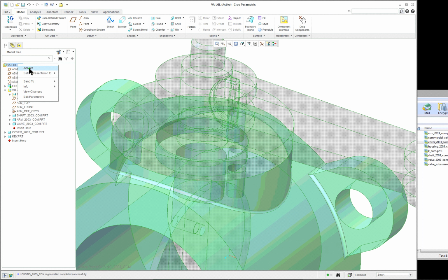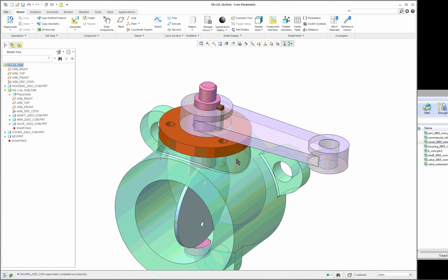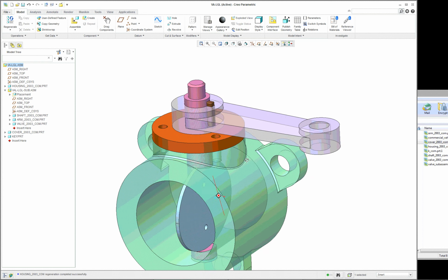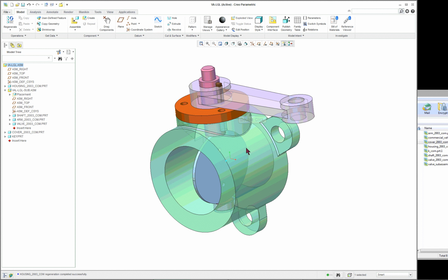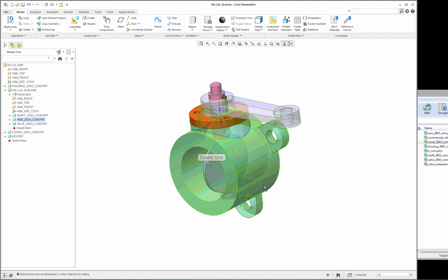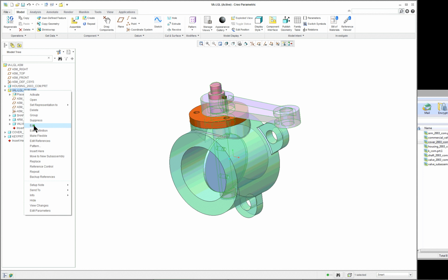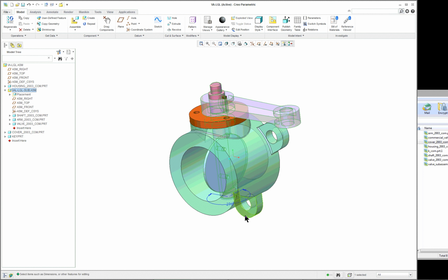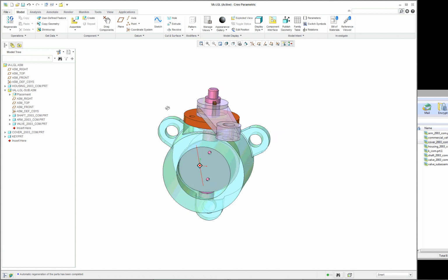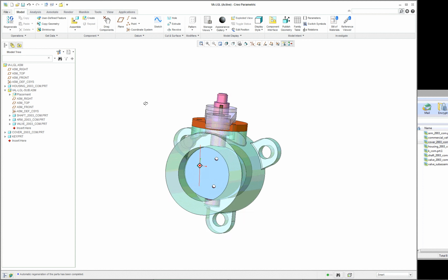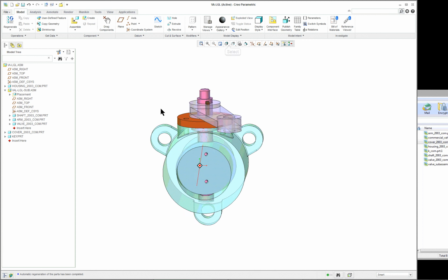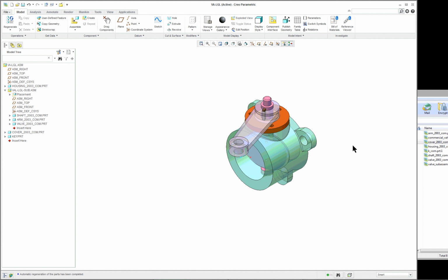And activate the assembly itself. Want to rotate it? Double click on, see if we can get it. Ooh. Let's click on the subassembly and select edit. And let's turn this to how about 200 and regenerate. And it turns it. Standard orientation, make sure you save your model.